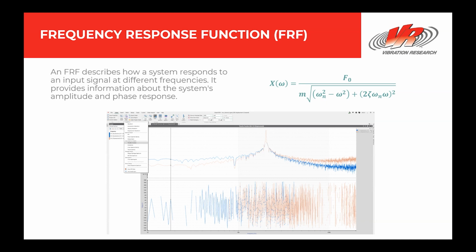In ObserView, transfer function graphs are essentially equivalent to FRF graphs, as the transfer function graphs are based on measured data, like what is traditionally referred to as a frequency response function, FRF. So for all practical purposes, they're the same thing. These graphs show the measured response of a system in terms of magnitude and phase across a range of frequencies. As such, they provide a practical representation of the system's behavior under real-world conditions, capturing any nonlinearities and noise present